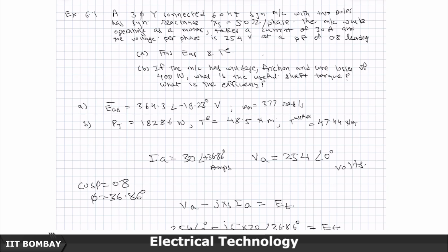Rotor winding is carrying a DC current and it is sitting on the rotor and rotating along with the rotor. So, the flux is not changing with time, and it will not see any change in flux with time anywhere. Therefore, you will not have any eddy current loss or hysteresis loss associated with the core. So, the core need not be laminated to take care of that.